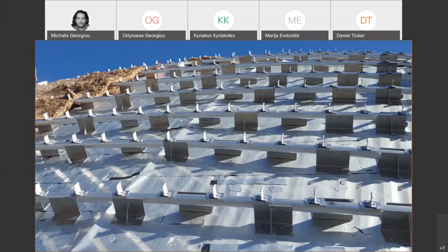And this image shows the inside of the dome shell. These are the tubes holding the skin, the secondary skin, the Kalzip-type standing seam roof. This needed to be placed with very high accuracy, otherwise the roof system, the standing seam system, wouldn't be able to interlock together. So it required really high accuracy.